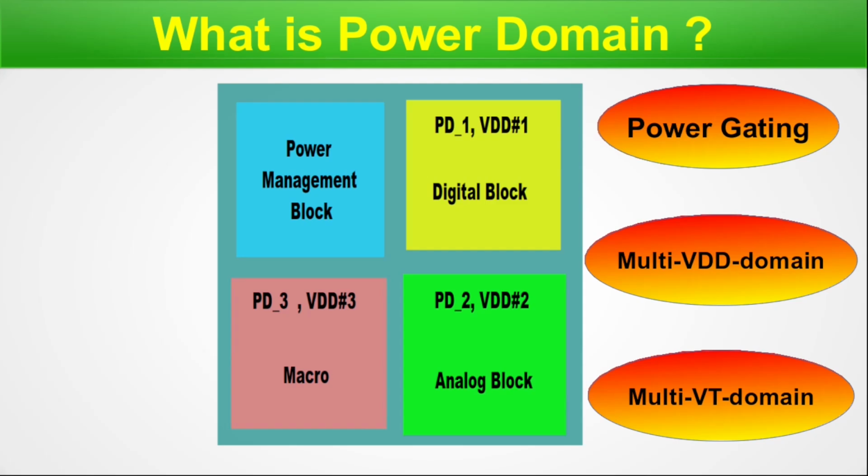Now, these are a few things I have talked about. Some other things will come at the left side. These cells I'm going to talk about right now. One is already displayed, that is the isolation cell. This particular cell isolates, and I have given the detailed description in the UPF series, so I'll not go into detail. But these cells are also needed in today's modern blocks where such multiple VDD blocks are there.